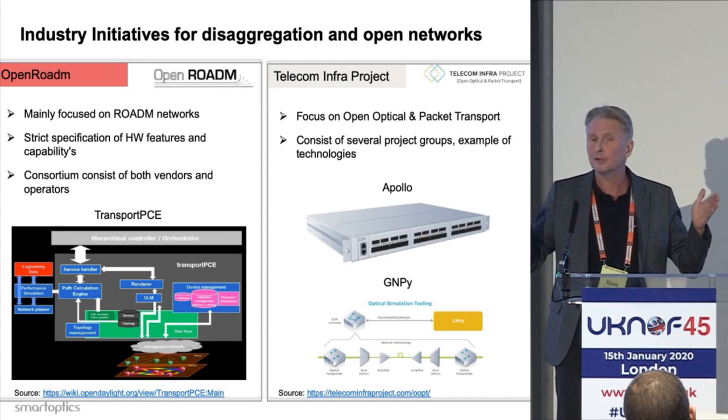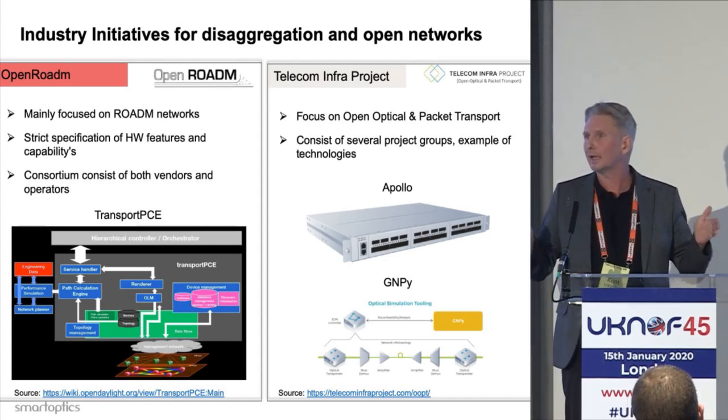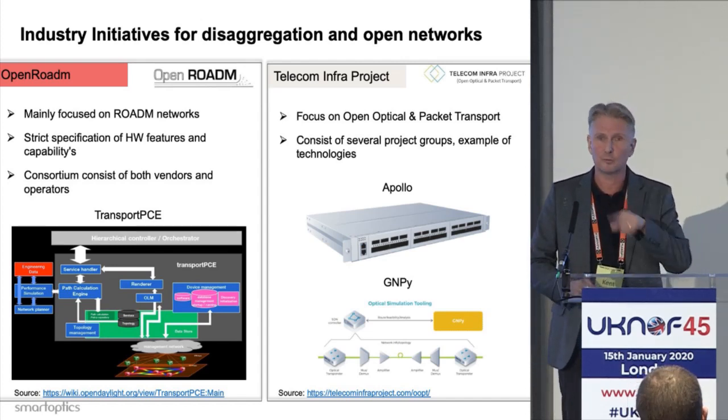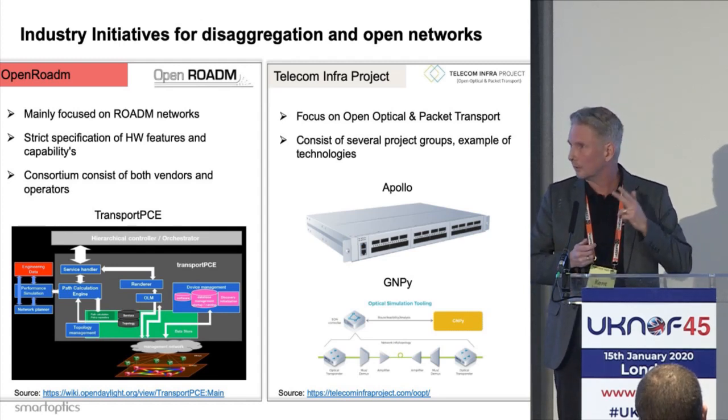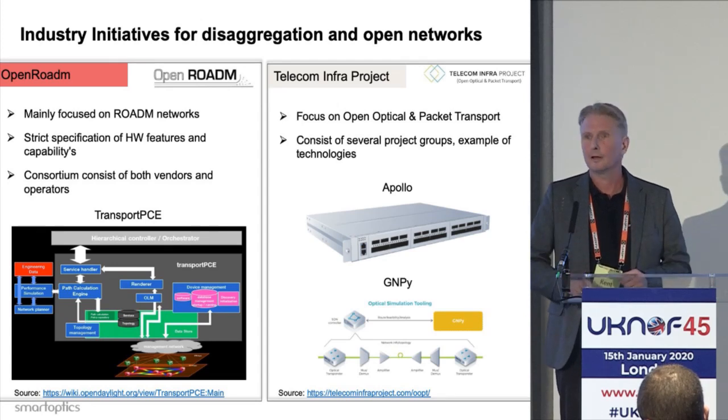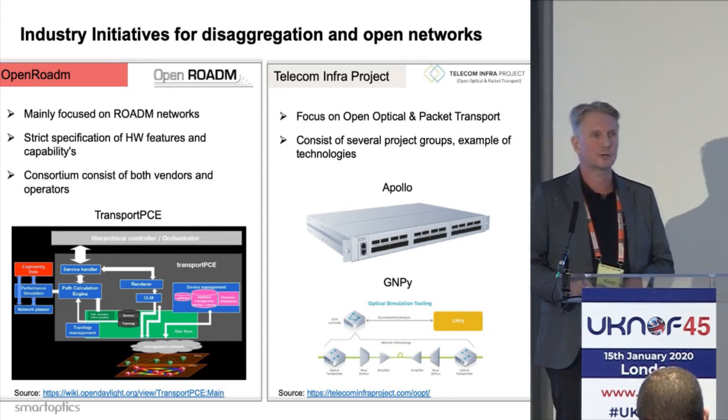So you can set up a network link, and from there simulate the optical performance and make sure that you can guarantee a certain bit rate, baud rate, distance, or spectrum efficiency through your network.